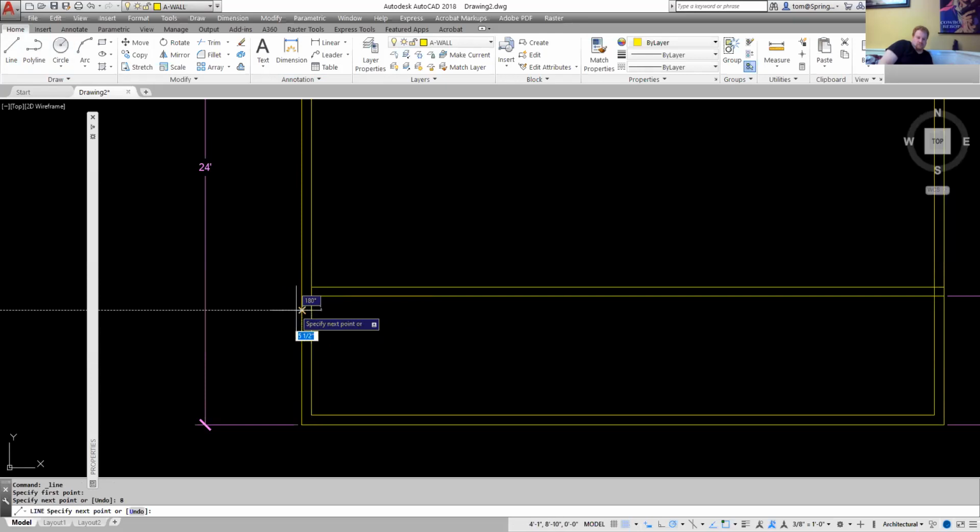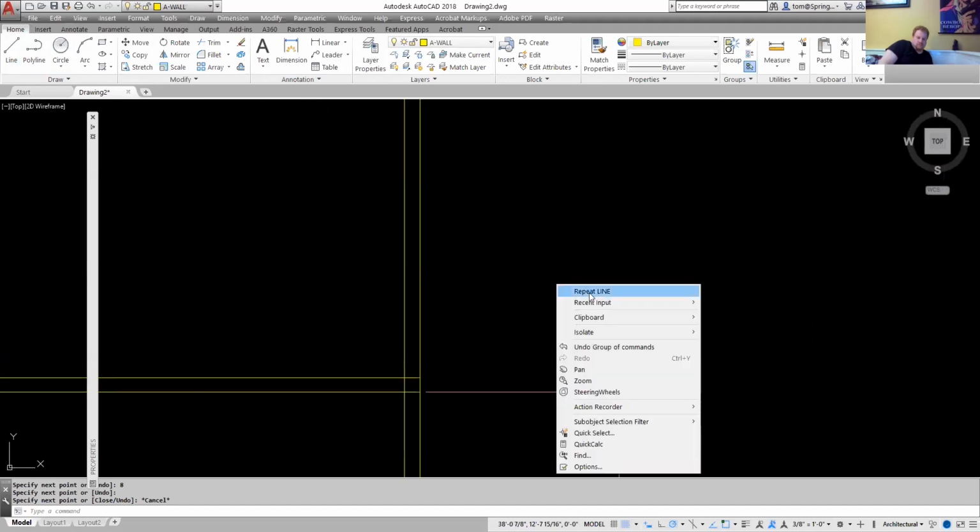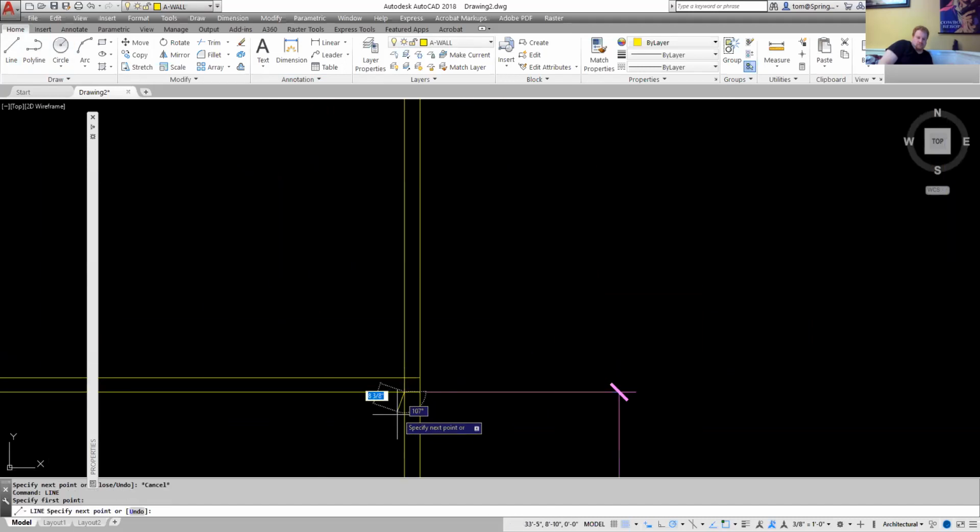Then over in this direction, like that. Now at that point, I could just go ahead and mirror that whole thing, okay? Because at this point, it is the correct size, and I could just go ahead and go down 8, and then over here. I could do that, okay? Next thing I'm going to do is trim it. To trim it, I'm just going to grab everything as a cutting edge by hitting my Enter key. And I hit my Enter key, everything's a cutting edge.